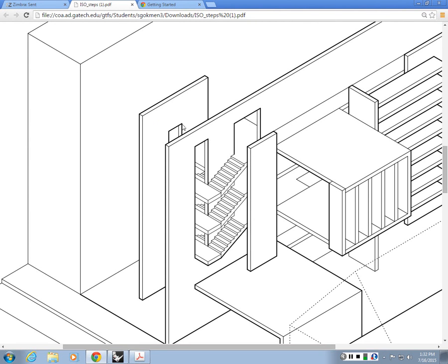And then also you can do the same thing for these openings. So this surface could be highlighted with thicker line weights, and this inner thickness could be thinner. And it helps you actually differentiate multiple geometries from each other, because you're highlighting the outline of it, right?